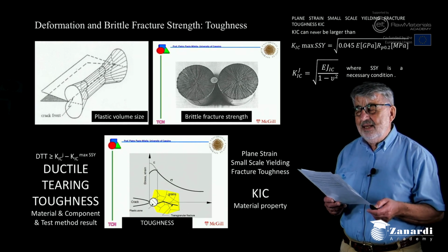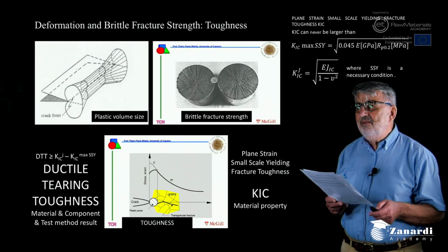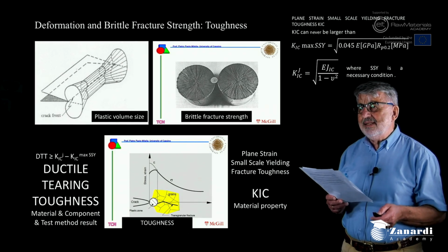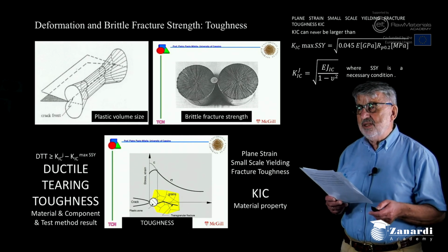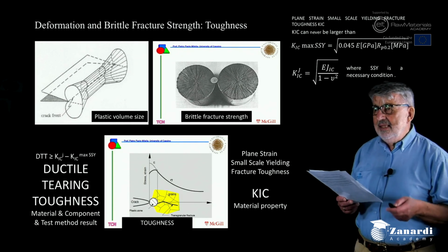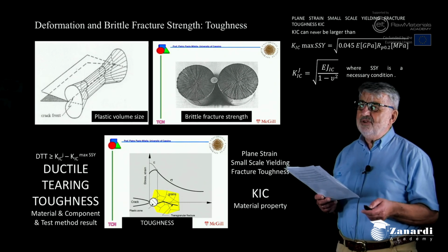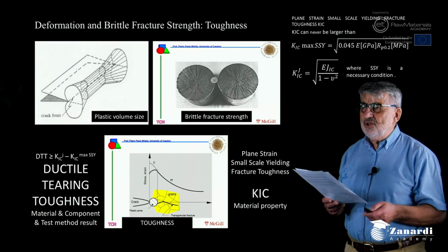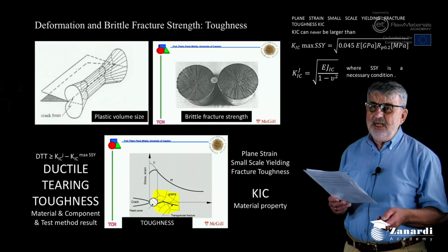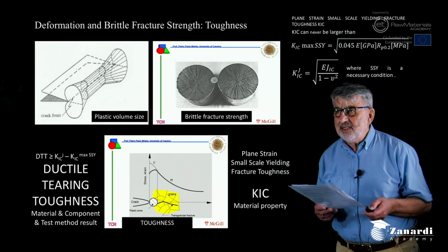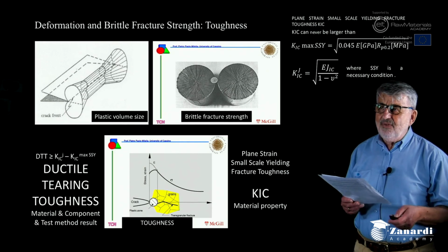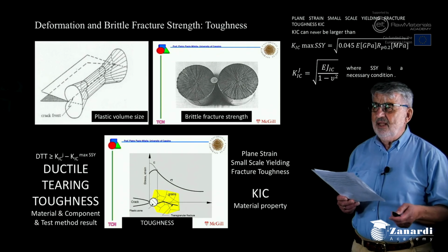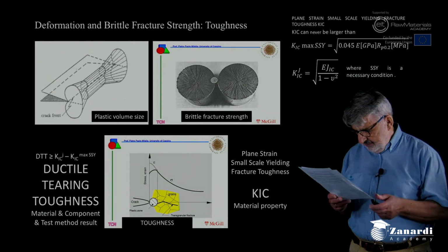And this is not always the case, even following existing measurement standards. And this makes a problem when you have to compare the fracture toughness of different ductile materials measured in different conditions with the different material standards.